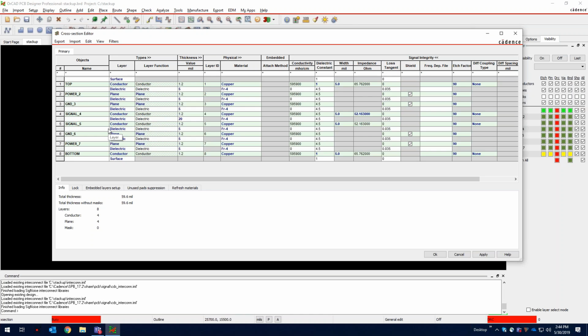This isn't a requirement, but it's recommended, as Matthew had said, to reduce the warpage of the board when it's manufactured. In this Stackup, you can see that a thinner core is used between the plane layers to increase the interplane capacitance and help reduce the effects of EMI. A thicker core is used between the internal signal layers, resulting in less coupling and reduced crosstalk.